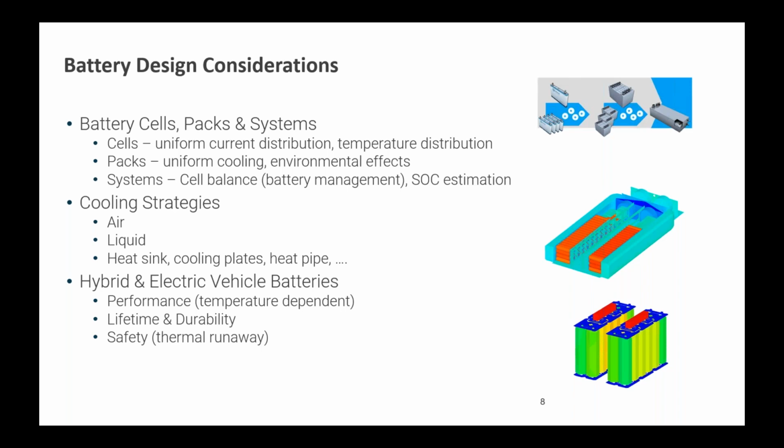And then the last one is safety, which is mainly looking at thermal runaway, and that's when a fault event happens and the battery goes into thermal runaway, which is an exothermic chemical reaction where basically it burns up. We want to make sure that we can either mitigate that to the point where the entire pack doesn't go up in flames, or at least give the occupants of a vehicle a warning and then time to escape the vehicle before a catastrophic event occurs.